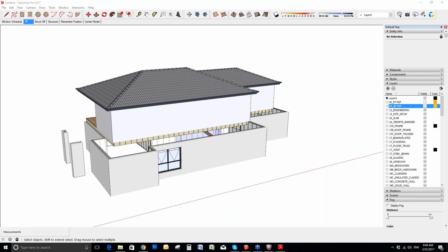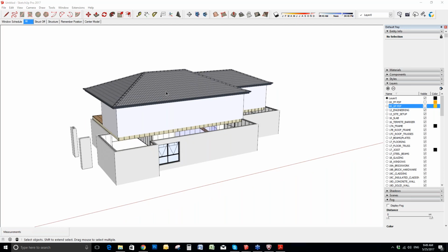The color for the layer, does it appear in the model to assist in copying plan? I assume that you mean the color by layer. As you can see, all of our layers have the potential to have colors associated to them. Some of them do, others don't, but you can always assign them yourself. You can actually use color by layer. It is different. I don't necessarily think it would help you copy the plan. You need to change to color by layer mode.